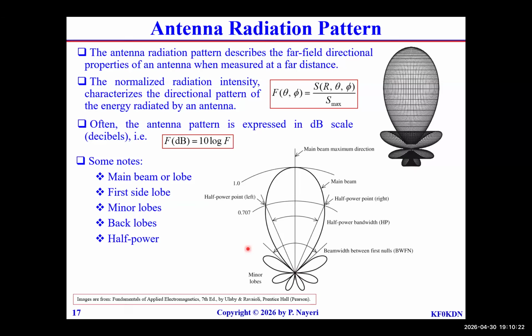But if your target is here, it would also detect it. So how low that side lobe is could have some important implications. In case of some antennas, such as Yagi-Uda or LPDA or types like that, you may have a strong back lobe here as well. So again, you have to pay attention to what type of radiation pattern you're looking for in any given application.